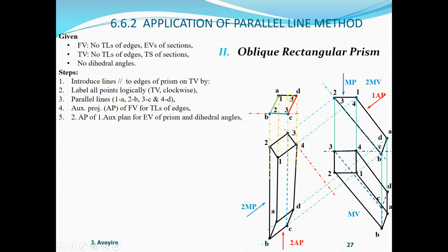So that is the true shape of our prism, and it gives us the perpendicular distance between the edges. So now we know the true length, and therefore we have to cut open along one of our true lengths. And the dihedral angle can be measured from this part here, from the edge view of the prism. We have the various dihedral angles, they are not equal here. Now we select the shortest edge here, that is 1A, and we cut open.